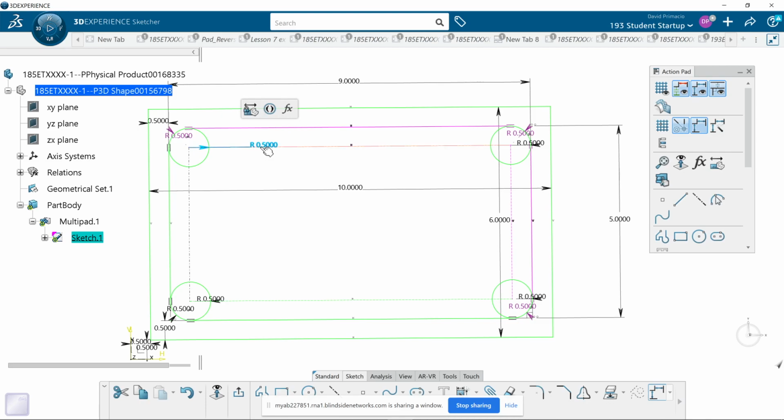Now, I was actually doing some fabrication on my trailer with the ex-Boeing guy, and he was talking about drill bits and tools. The 1/2 inch tool would be a certain price, but to get the next size down, you have to pay 4 or 5 times as much for that tool. So the more common the tool or cutter you can use, the cheaper it is for the shop. Plus, that's what most shops have, the most common ones. The more tool changes you do, the more expensive it is.